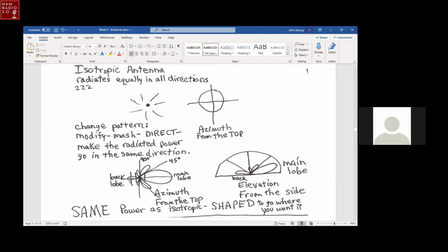Because with the Yagi antenna, you expect lots of gain off the front, and you want a good front to back ratio so that you can set the backside against interference and not pick up the interference power, but you want to pick up all the power your Yagi's pointed at. And there are side lobes on Yagi antennas. That's these other little lobes coming out the sides.